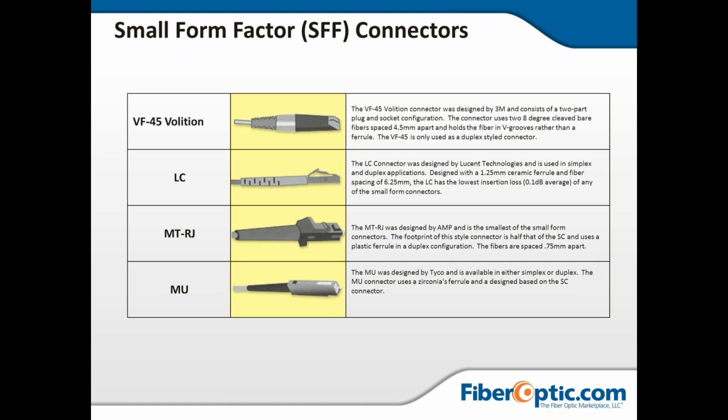The LC connector, which was designed by Lucent Technologies and is used in simplex and duplex applications, has a 1.25 millimeter ceramic ferrule, and they really feel that that's the big difference, with the fiber spacing of 6.25 millimeter, has the lowest insertion loss. It's 0.1 dB average of any of the small connectors.